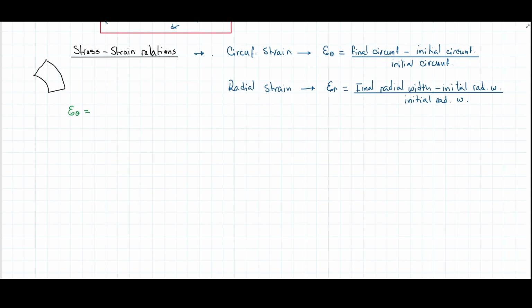Awesome. But then when that starts moving and all these stresses appear and the whole, let's say, rotation is applied to the disk, it's going to deform into something like this. Let me see if I can draw it nicely. So it's going to try to expand, something like this. I'm going to exaggerate the deformation because of the rotation, all of the stresses appearing there. So this is very exaggerated, how this is going to expand.